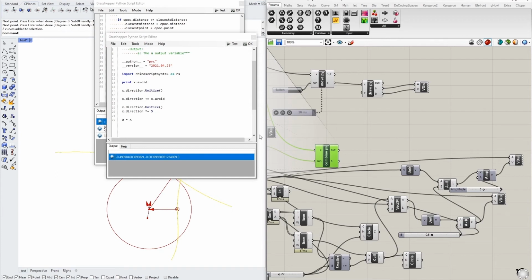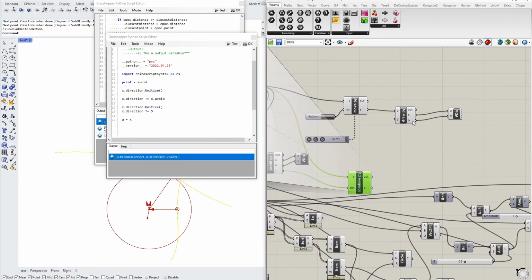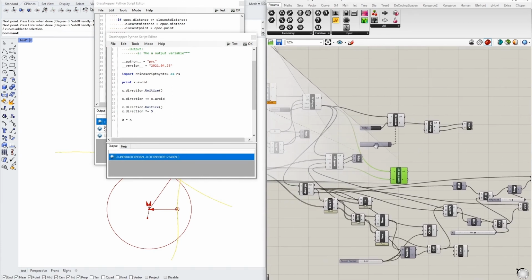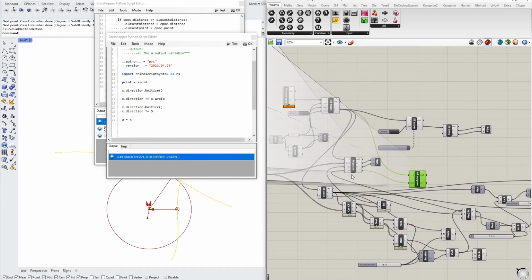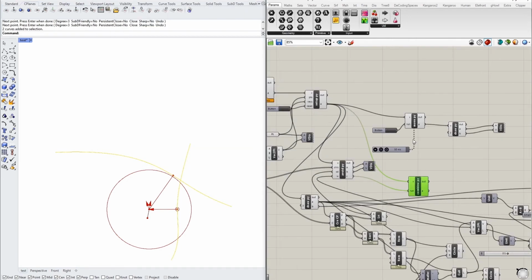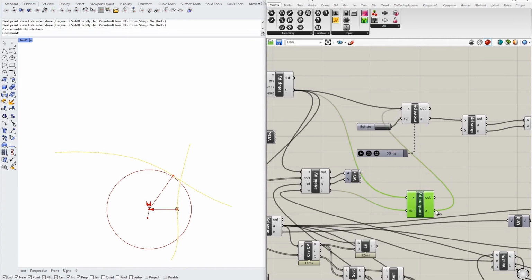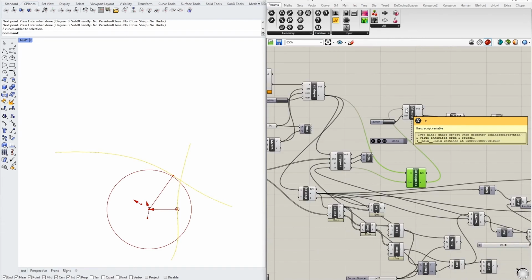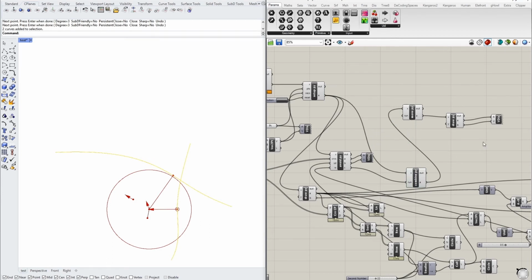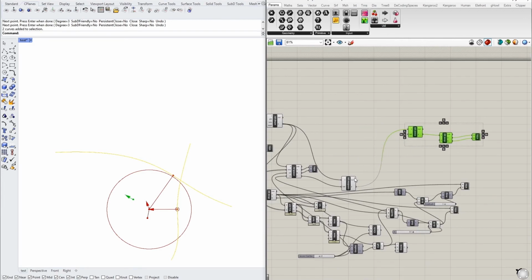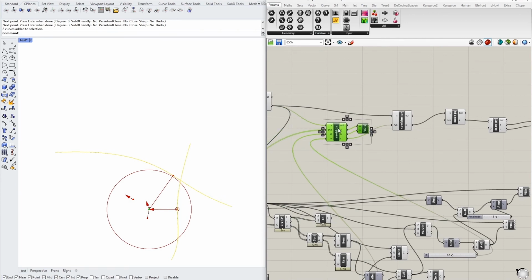At this point, we are now ready to attach what we have done so far to move, draw, and visualize as the complete process that we can iterate over time steps. So let's close the editor for both avoid and combine, and we will connect the output here with move. And to run the process over multiple time steps, again, we will need to relocate the button here and the trigger. Let's delete this. And let's rearrange some of our nodes so that we can see clearly where it is.